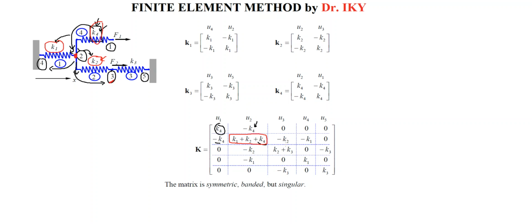So I'm going to continue with minus K2, and plus K2. After that, there is a connection between K2 and, look at here, K3. So I will take K3 then, plus K3, but look at here, the fourth node is here. So there is no connection with the third one and the fourth one. Because of that, you will make 0 here. There is no connection. What is the connection? Connection is going through fifth node. Because of that, you will make here 0 and then jump into fifth column.